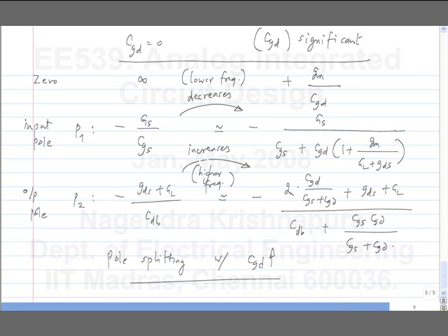Now this is something that we use widely, first for analysis, we want to know how the common source amplifier behaves, and secondly for design. Like we said, this pole splitting phenomenon is useful for frequency compensation. So we will use it by increasing the value of CGD. I think you are already familiar with what is usually called Miller compensation. You put another capacitance across CGD and you emphasize this pole splitting until a point where only one pole is dominant.